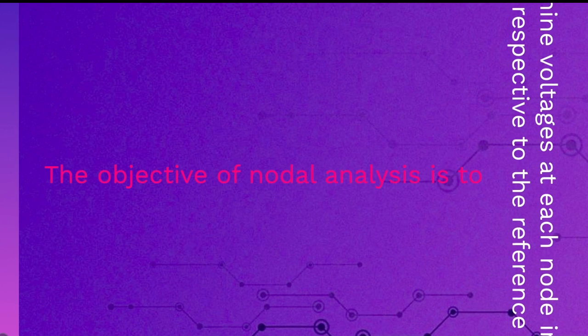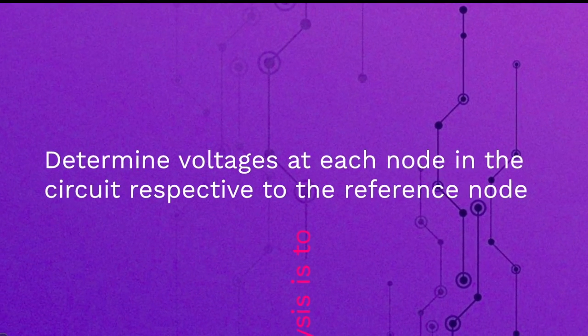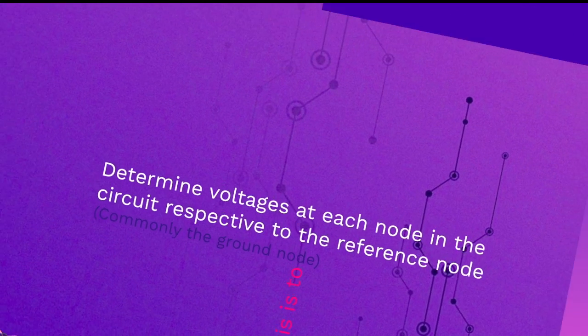Now, what is nodal analysis? Well, the objective of nodal analysis is to determine unknown voltages in a circuit in respect to a reference node of known voltage, which is commonly the ground node with zero voltage.